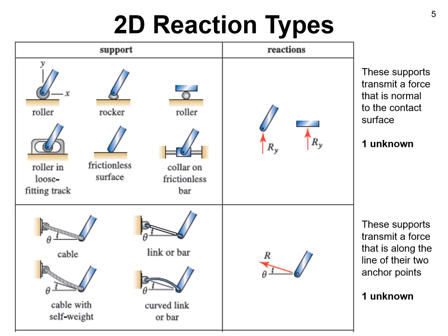And we again have one unknown force, because we'll assume that the angle theta is given, but the magnitude of the force is not given. Let me also note that springs are of this category. And finally, in none of these examples do you see a torque, because in all these cases it's clear that the objects would not be resisted if you try to rotate them. So there would not be any torque in any of these situations.